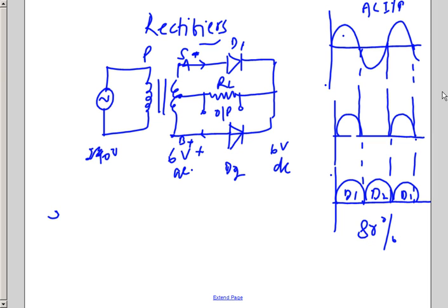If you see in the market a low cost charger and a high cost charger, this will be the difference. A low cost charger will not have filters. It will be in pulsating form, and a little bit of AC is mixed into the output, which can damage your appliances like electronic gadgets or mobile phones. So to purify that, we again have to use filters using a capacitance and inductance. So that the output will be in the pure form of DC.